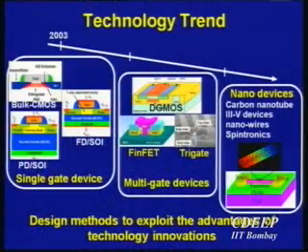And there are various interesting scenarios that one has to look at. And there's a need for some sort of device-circuit co-design to get optimum performance out of these devices. And the reason I say that is because when it comes to these FinFETs or multi-gate devices, you can potentially have multiple fins in order to increase the strength of your devices. Meaning thereby, in a bulk device, when you change the width of the device, you can get larger current. In these kinds of devices, increasing width would actually mean making these devices taller. But then again, from the mechanical stability point of view, that sometimes is difficult. So a better way of doing that is to have multiple fins. So those are like parallel transistors.